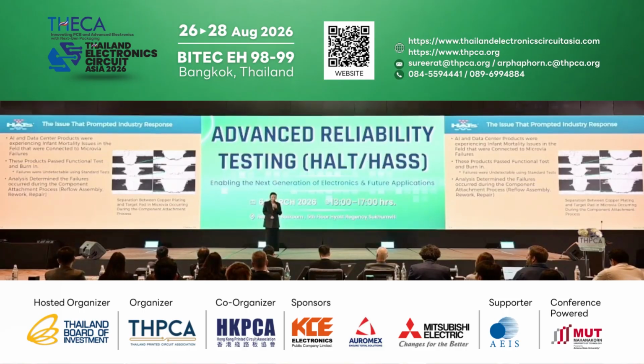If you look at the graph in the right corner of the slide, the failure they saw is a separation between the copper plating and the target pad in the microvia, occurring during the component attachment process.